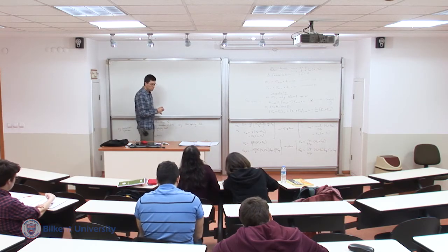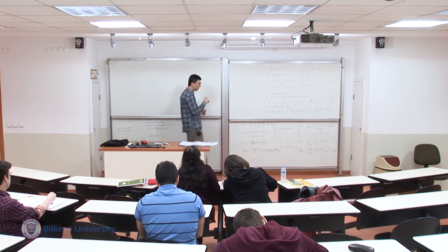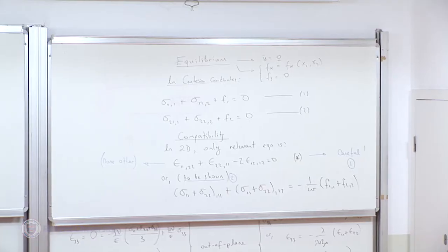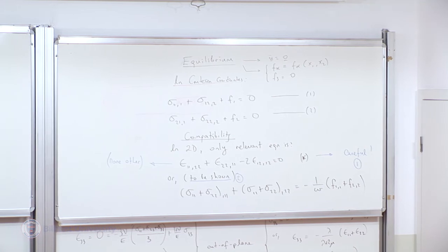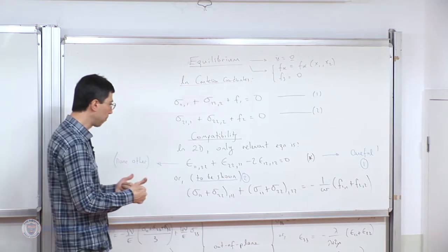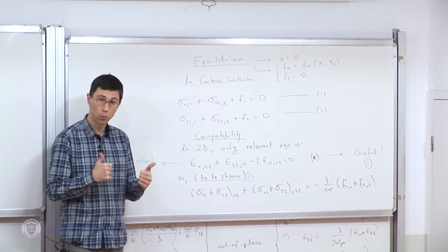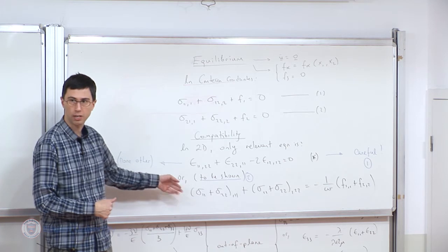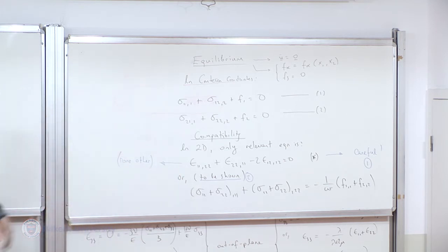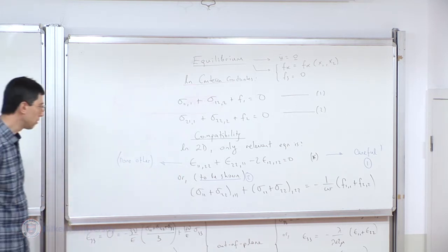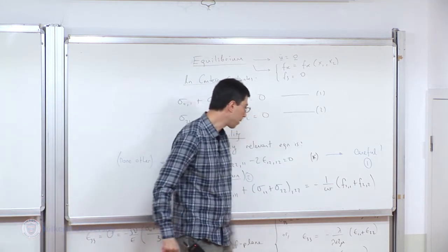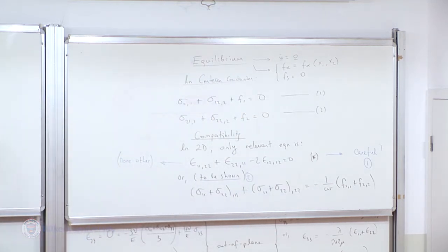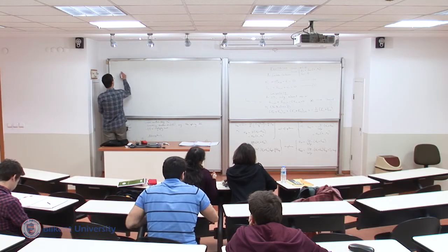Okay, so now I'm pretty much done with the basics. So I've shown you that plane stress and strain problems are cast in a unified setting, but eventually we want to work towards a stress-based approach. The stress-based approach works in an intrinsically 2D setting. Eventually, it doesn't matter whether it's plane stress or strain. The equations we'll be using are identical, at least functionally, right? The only free parameter, let me say, is omega. Okay, so those two remarks are the two things that I'd like to spend a little bit of time on now.